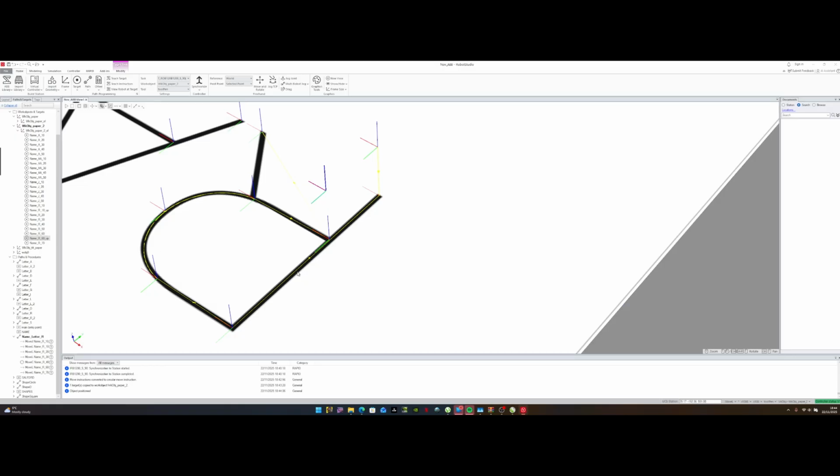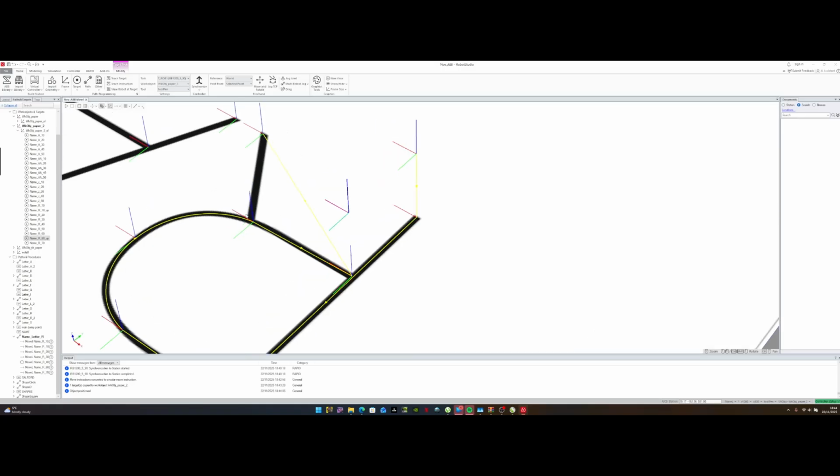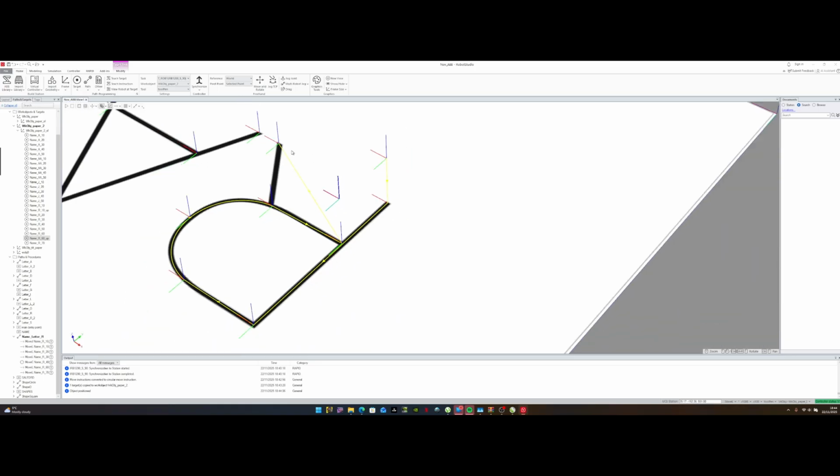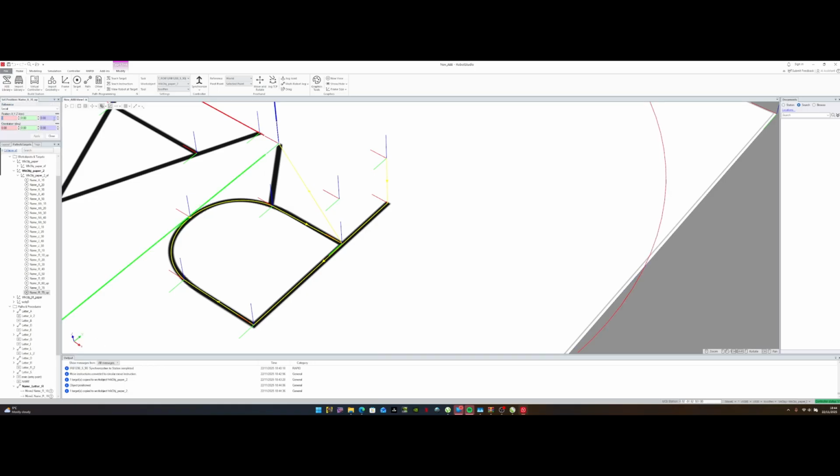So I want the robot to jog here and then jog linearly up before going over here to write the next one, okay? And just because I'm nitpicky, I also want it to move in the air over here and then come down straight. So I'm going to make a duplicate of this again and do the exact same thing I just did. Up. And now come over here, right click, modify target, set position, and I'm just going to set this to 15 as well. Apply.